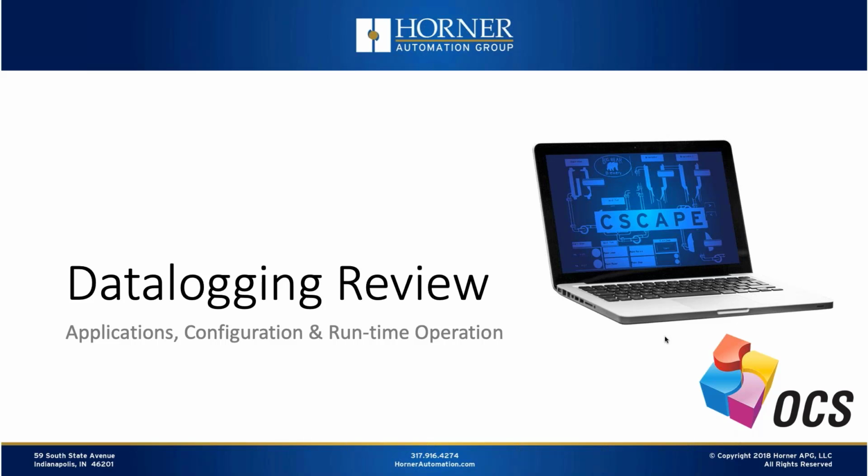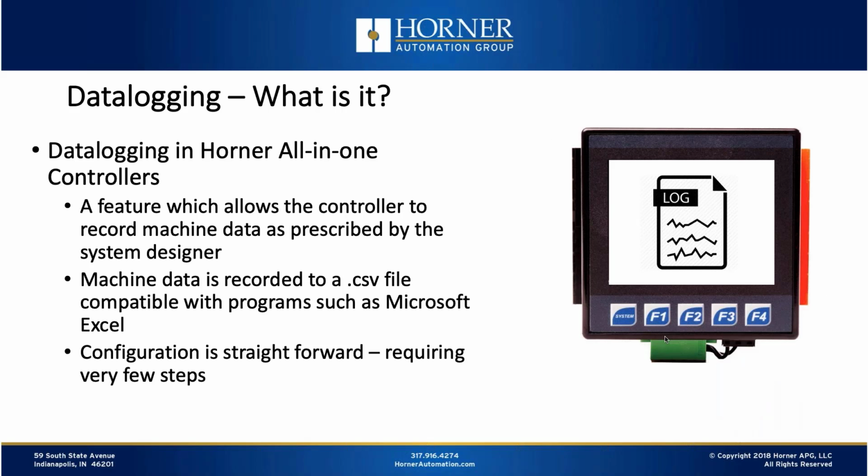So let's start off with the data logging review. All right, so what is data logging? Data logging is a feature which allows any of the Horner all-in-one controllers to record machine data. And that machine data is going to be data logged as prescribed by the system designer. So whatever process information or machine data that you care about in terms of recording on a regular basis, you have the ability to record that information. And then that data log is recorded in a CSV file, which is compatible with a lot of programs, including Microsoft Excel. And configuration is really straightforward.